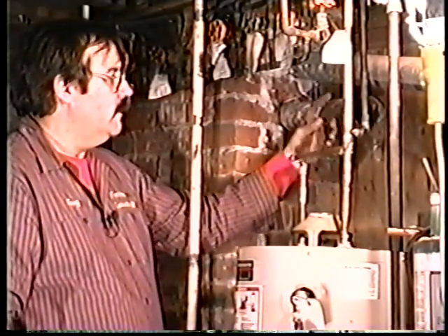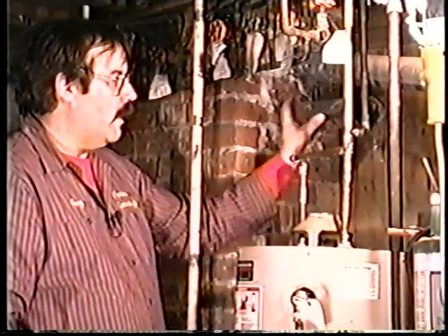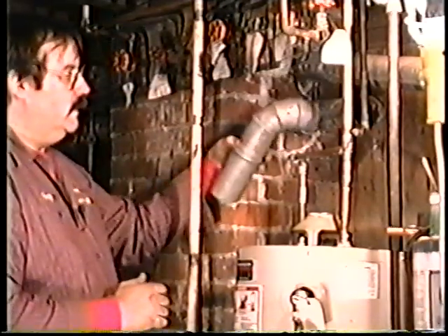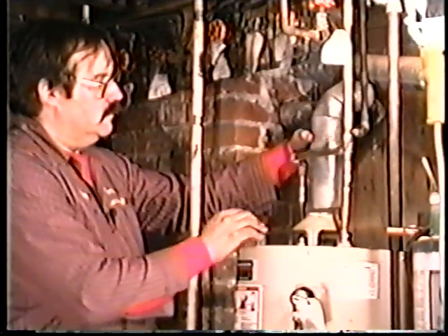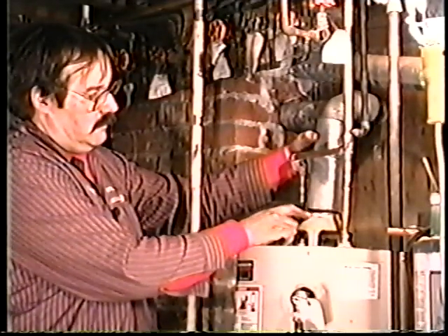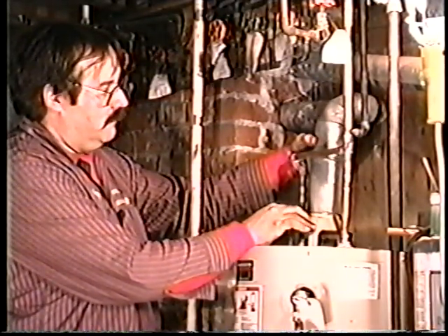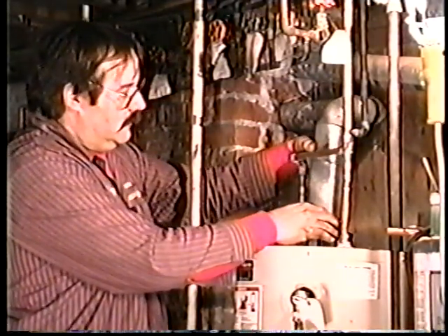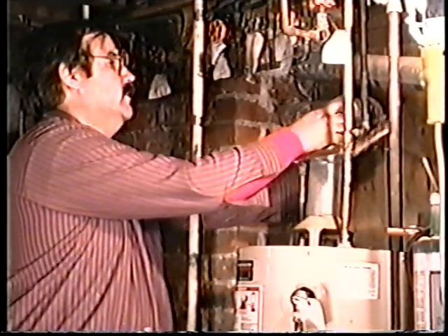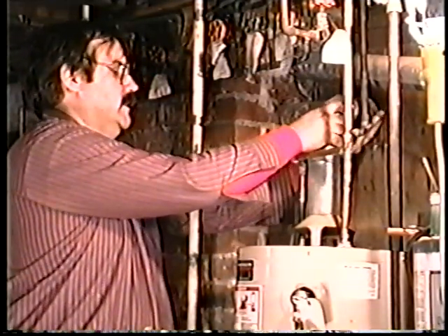the chimney from the water heater to the connector of the chimney. Basically, we're going to use a vertical piece and a 90-degree elbow to finish and make our connection. The top of the draft hood has a connector on it that the flue pipe goes over, slides right down over it, and then the last connection is made into the 90-degree elbow from the existing water heater.